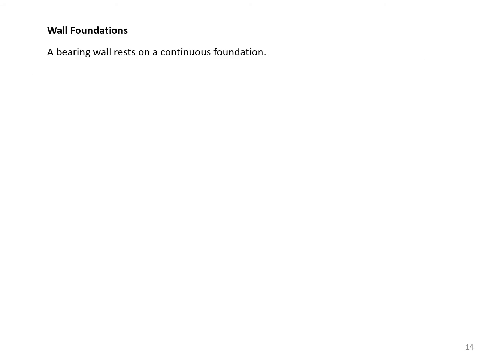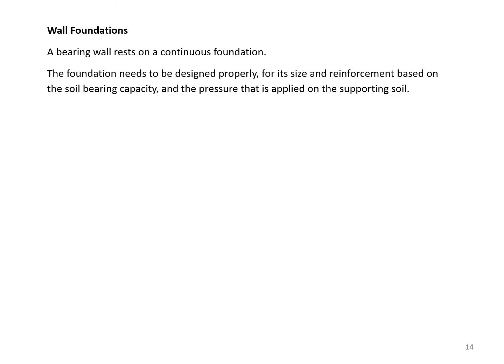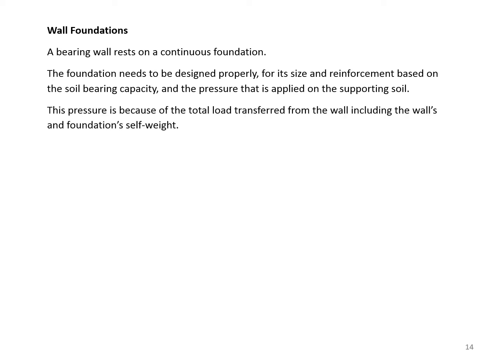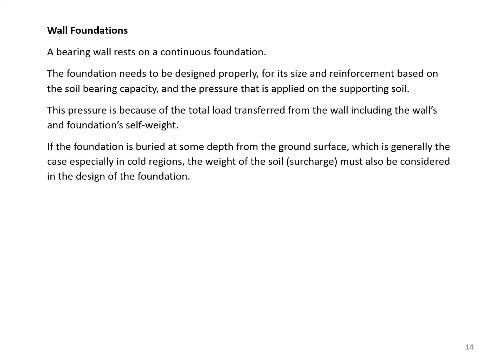Wall foundations. A bearing wall rests on a continuous foundation. The foundation needs to be designed properly for its size and reinforcement based on the soil bearing capacity and the pressure that is applied on the supporting soil. This pressure is because of the total load transferred from the wall, including the wall's and foundation's self-weight.